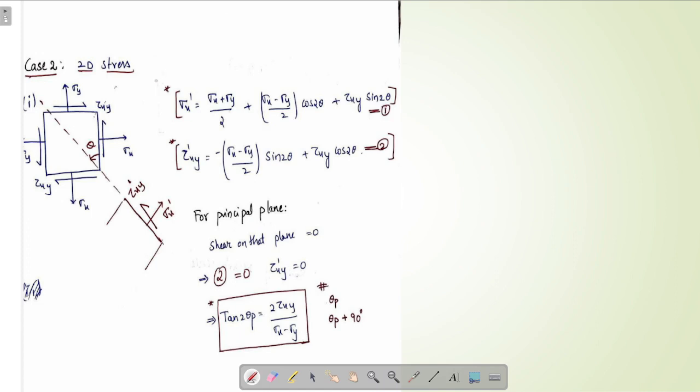So, we have seen the sign convention part. Now, let's see these formulas. The sigma x, sigma y are the normal stresses. Tau xy is the shear stress. Theta is the angle with sigma x plane. We have seen this in the sign convention part. Then the normal stress acting on this plane is given by this formula, and shear stress acting on this plane is given by this formula. Okay, we have to remember these formulas. These formulas are very important. Remember this negative sign also, and don't forget to remember the sign convention part. It is the most important thing to remember.